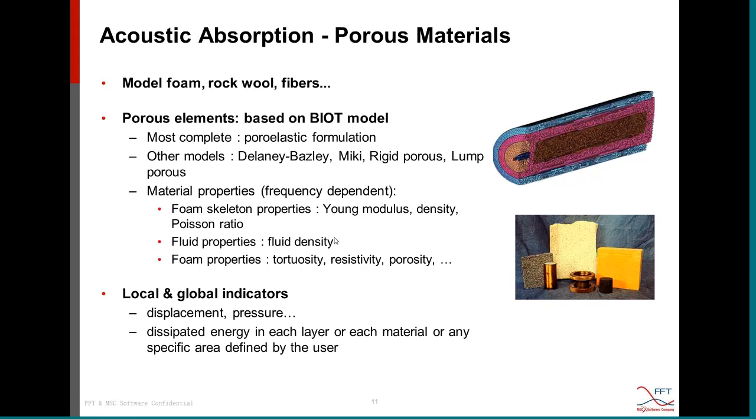And with simulation on porous material, we can output not only some local displacement or acoustic pressure in the porous material, but also a very interesting indicator, which is the energy dissipated by the porous material. So this will give some insight on how the material is damping acoustic power.